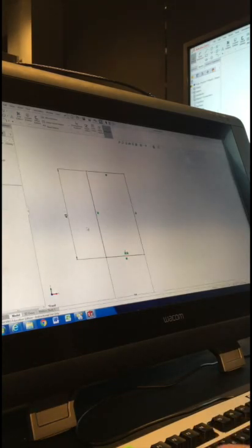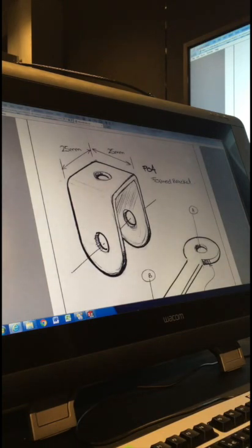So when we're doing our offset shape here, we're doing this shape from the side. It makes a lot more sense to do these curves now before the offset, because that way the offset will include them for us. We don't need to work it out separately. So what those are called there are fillets, all right? So a curve around the edge.